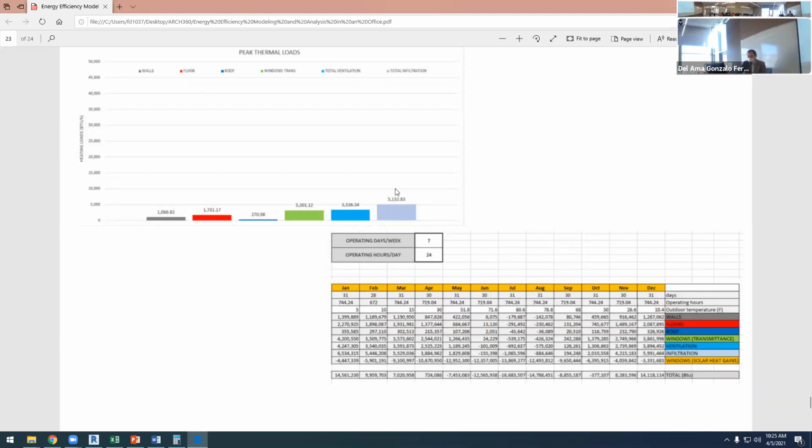So this is a perfect building, or almost perfect, because you met all the standards. You have selected the best glass, triple glazing, low emissivity. You have selected a heat recovery. So on a perfect building, the most important heat loss is the infiltration. Oh, we can say, no, it's the window. No, it's the infiltration. So, in this area of the world, infiltration is relevant. In other areas of the world, it's the other way around.